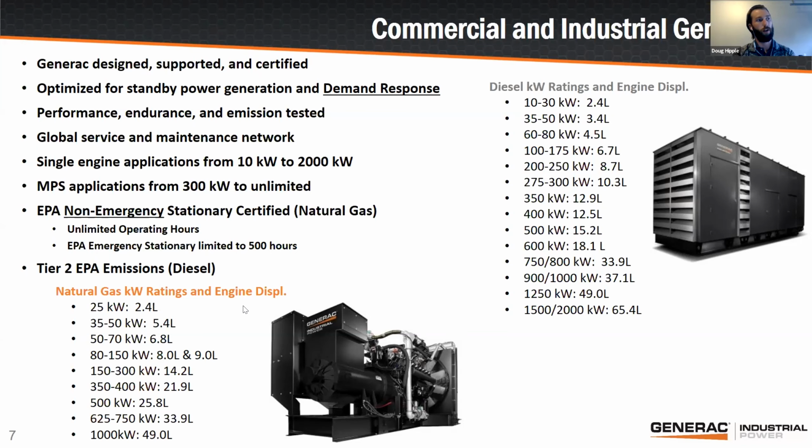Our units can fire up within 10 seconds notice and take the full load or the full requirement from an electrical capacity standpoint. And then they can run as long as you need, multiple days on end. I know in some more remote or rural areas, especially during PSPS events, we've seen folks out of power for as long as 2 weeks, and the generator, as long as it has enough fuel and is connected to a fuel source, whether that be a propane tank or directly piped natural gas, that generator will run as long as it has fuel for.